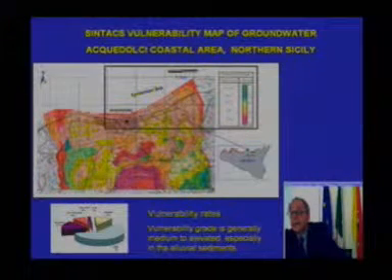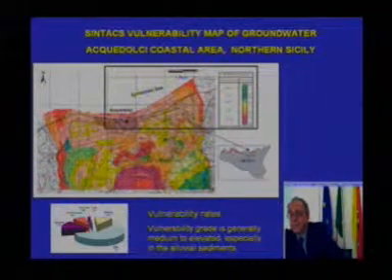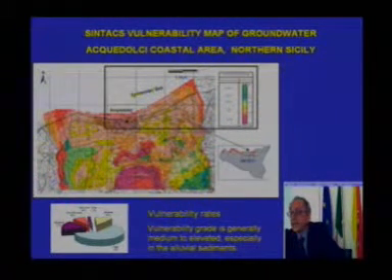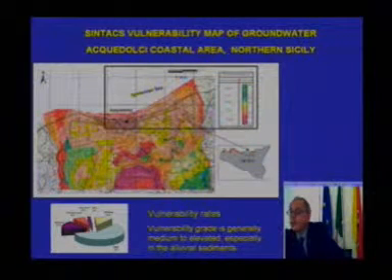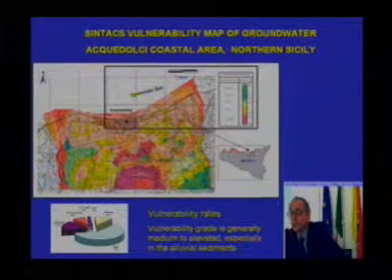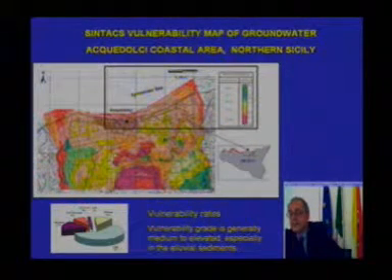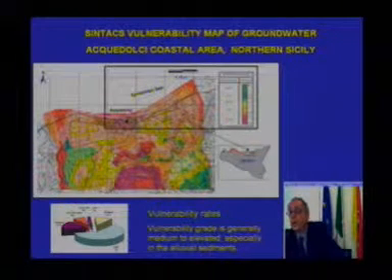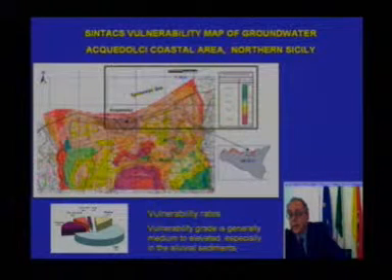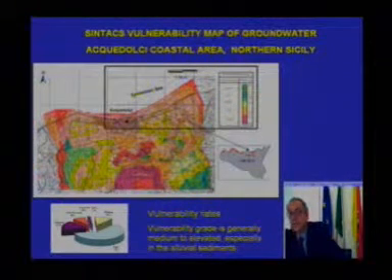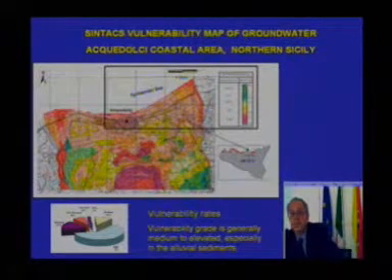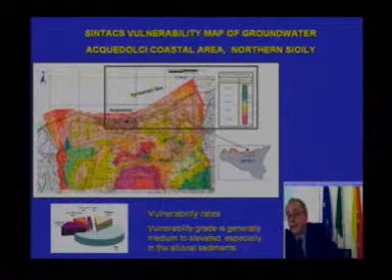In this area, the features of parameters, especially hydrogeological parameters such as hydraulic conductivity, are non-linear, and this complicates the question and makes the problem very difficult to solve because of the non-homogeneity of the aquifer, especially in the alluvial fan near the mouths of the torrents.